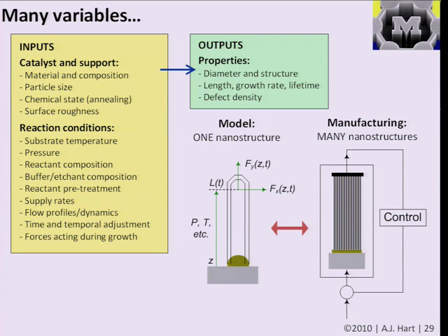And as we saw from the previous slides that showed the atomic model and showed the examination of the interface, our ability to model the growth of one structure is still really at an infancy. There are a lot of places in which we don't understand how the atoms are really incorporated in the structure. And we're maybe able to say that if you have an iron particle of 1 nanometer diameter, you get a 1 nanometer diameter nanotube, say plus or minus 0.1 or 0.2 nanometers. But we don't understand, for example, why the nanotube has one chirality versus another chirality. And this connection is bound to improve over a few more years of research.